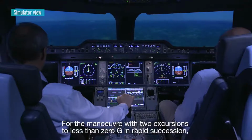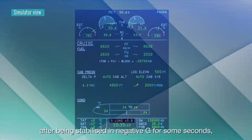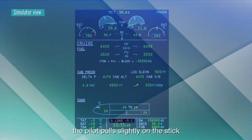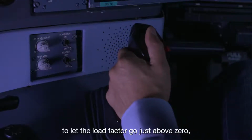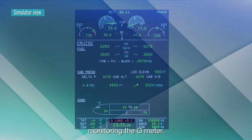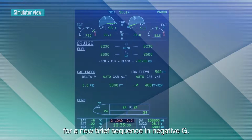For the maneuver with 2 excursions to less than 0 G in rapid succession, after being stabilized in negative G for some seconds, the pilot pulls slightly on the stick to let the load factor go just above 0, monitoring the G meter. As soon as the load factor is positive, he pushes forward again for a new brief sequence in negative G. Then the test is over and he can recover.